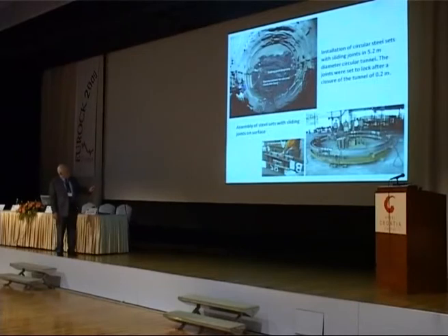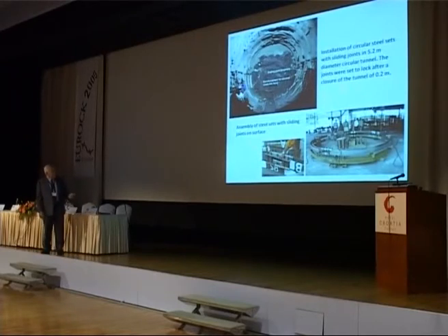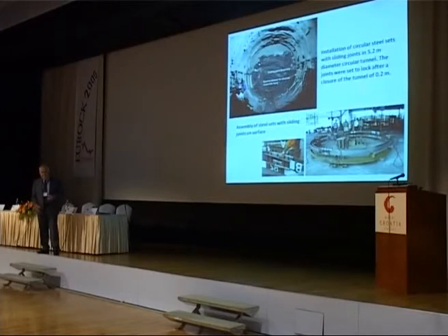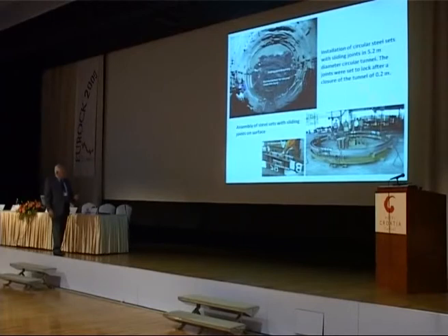Here you see again the graphitic phyllite at the face, and here are the windows in the steel sets with reinforcement for the inner lining in place. They were very simply constructed on site, with a fairly crude sliding joint, but they did the job effectively for this particular application. As I say, there are many other systems. Professor Wolf-Schubert has developed other systems, and there are others around that do this late engagement of the support.